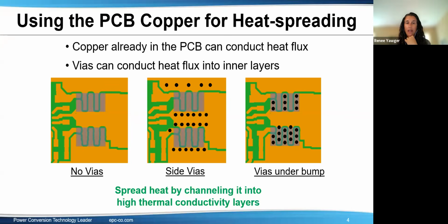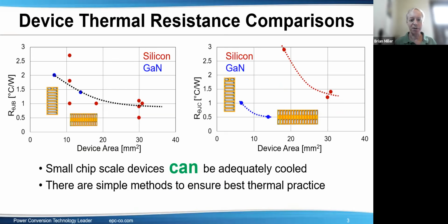For EPC GaN FETs, is it better to put the heatsink on top of the FETs or on the bottom on the other PCB side? On the top, on the top. Yeah, that's a very good question. It comes up every so often. EPC FETs are not designed to be top cooled or bottom cooled, they're kind of both. There's good conductivity from both the pads down to the board and from the top out.